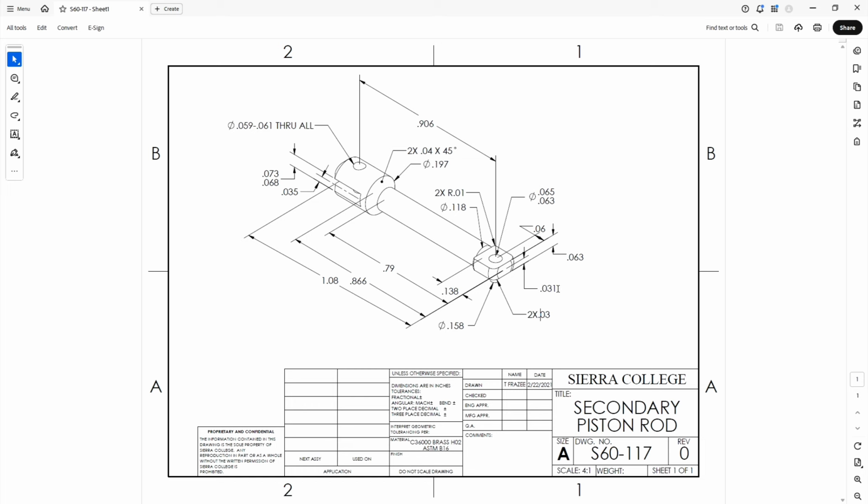Actually, ASME Y14.5 would round the top number to the closest even number, and then it would split the difference. So for this, we're going to put in a 16th here, and we're going to put a 32nd in for the decimal equivalent for these two dimensions.